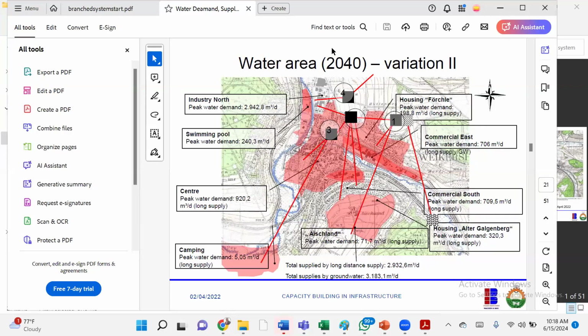We said that the base nominal pressure we expect in our pipe network is between 2 to 3 bars. But the upper limit is 8 bars. And we also say one of the reasons for this is because some of the pipes and the fittings and whatever you have in the market cannot take anything more than 8 bars. Only in recent times have we started seeing pipes that are 12 bars, 16 bars. But then, have you considered the connections too? Have you considered the tail end of those connections? So can they really take pressure more than 8 bars? The answer is emphatically no. So you must stick to that standard. You must make sure that 8 bars is not exceeded in your system.